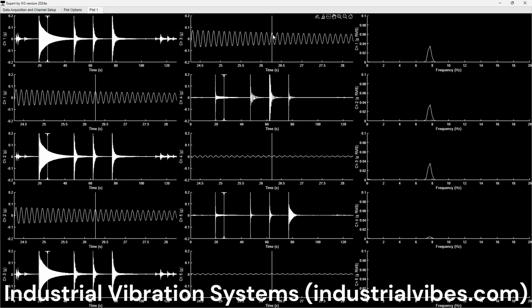So that tells us that at this frequency, which is dominating at the moment, the 3 vertical channels are all in phase. That tells us that it must be the bounce mode. And we can also see from channel 4 here and 5 here that there's not much going on horizontally or axially. So that tells me fairly clearly that this natural frequency here at just below 8 Hertz is the first bounce mode. So the plate is moving vertically.